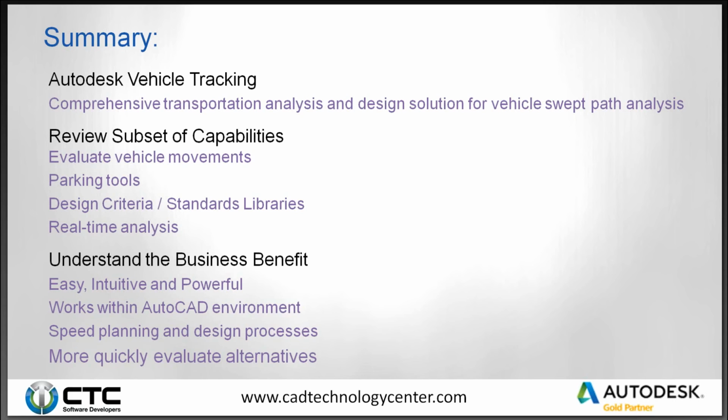Like I said, it works in all AutoCAD environments, so just AutoCAD, AutoCAD architecture, civil, map, anything that runs on an AutoCAD platform. The speed in planning and design. Oh, 62-foot truck can't make it, let's change the radius of the curb, and then evaluate extra alternatives.